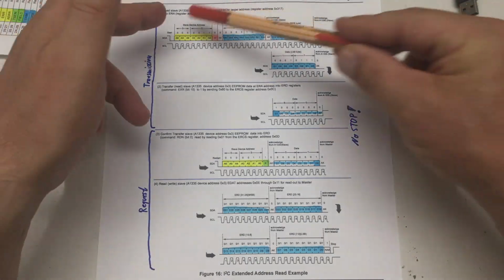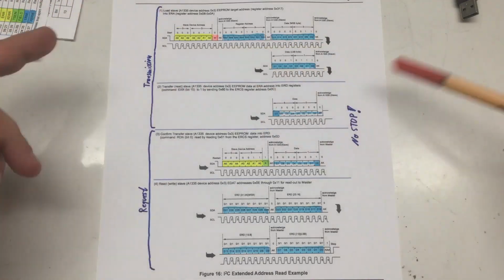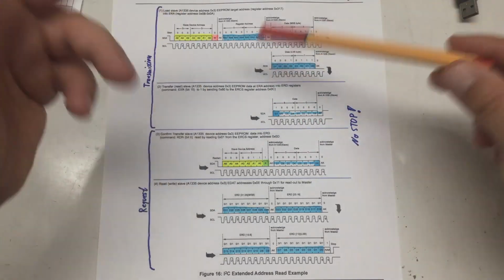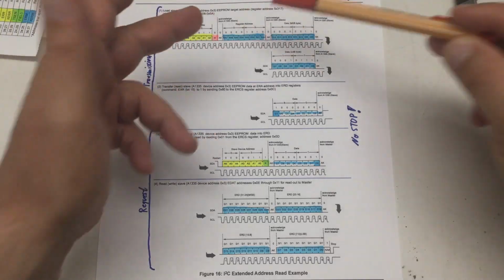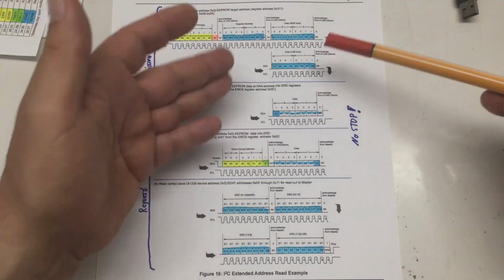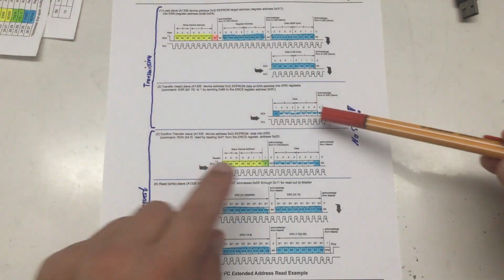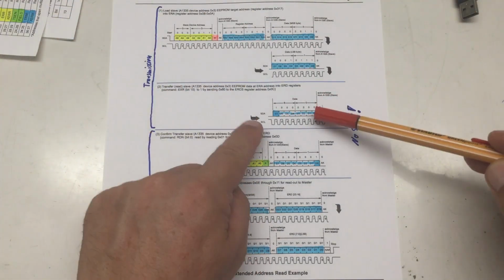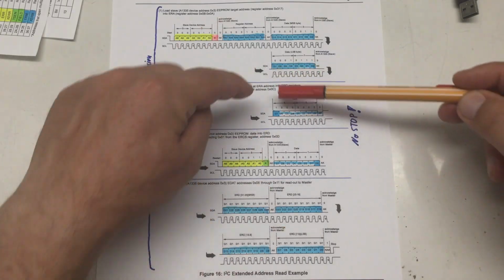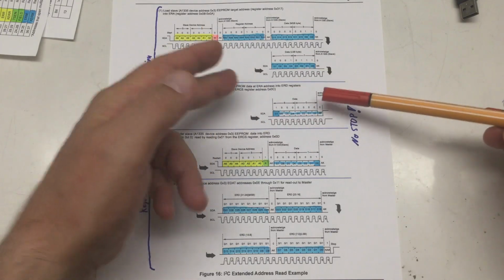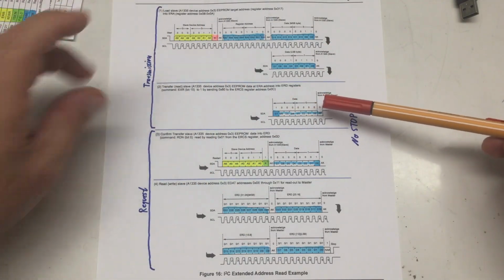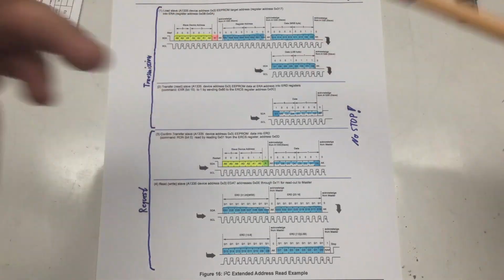Step 1 where we transmit something to our A1335, basically loading the extended read address register with the 16-bit extended address we want to read, and then we set in the extended read command and status register, just in the first byte, the read execute bit. And that concludes our first transmission and only transmission for that case.